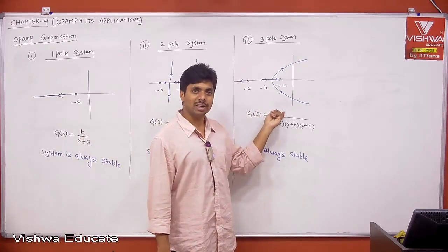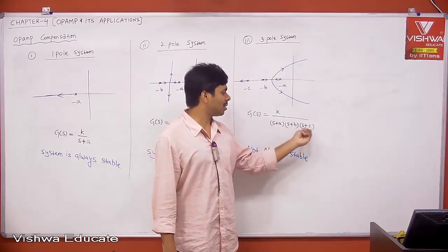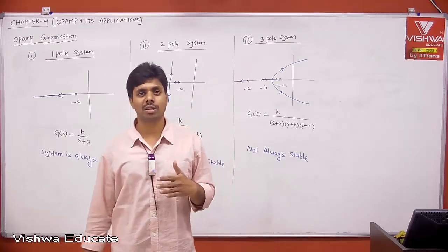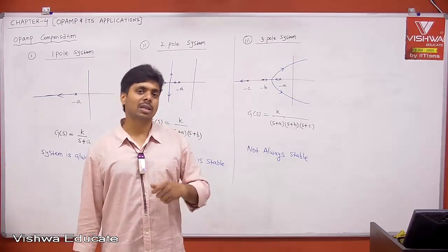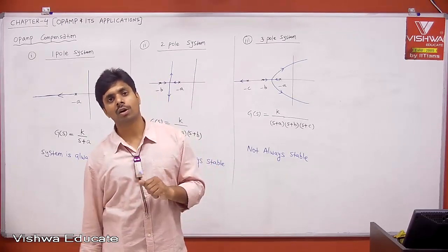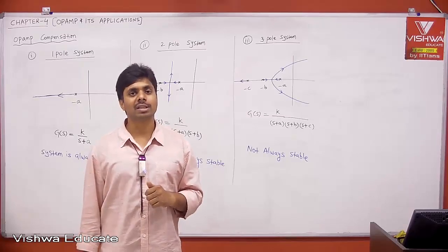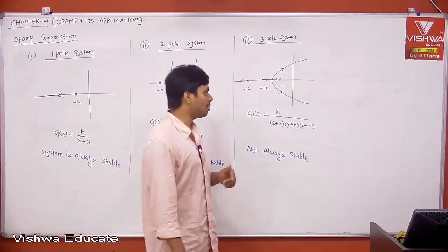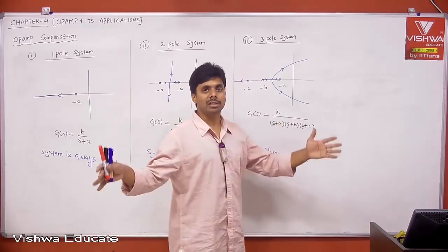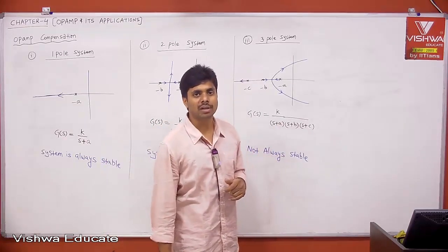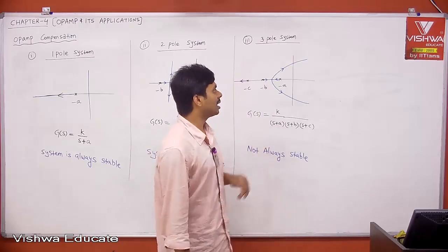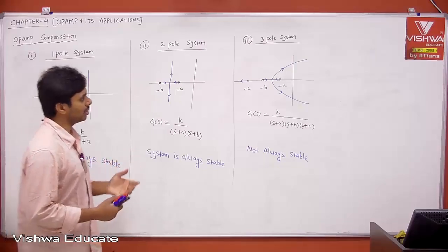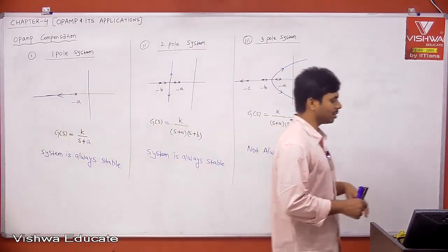If that is varying, then the poles are because of what? The internal capacitance or parasitic capacitance or the load capacitance, whatever you have for any system, that is the output impedance of the system, and the load cap of your system will give you a pole. An RC combination will give you a pole. Therefore, how many poles there are from input to output depends on the number of stages you have; that defines the number of poles. Okay, that is fine. Therefore, the system is stable or not stable. Everyone understood? Okay, this is the observation.